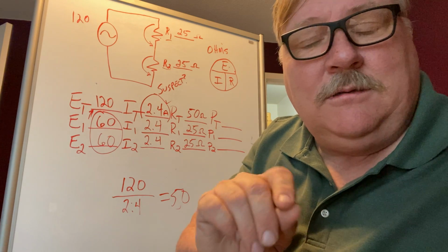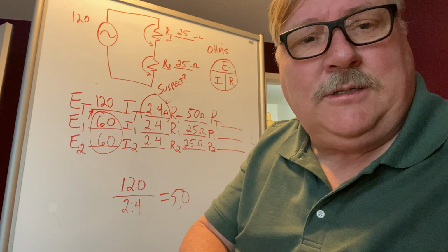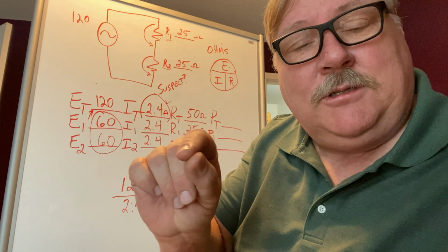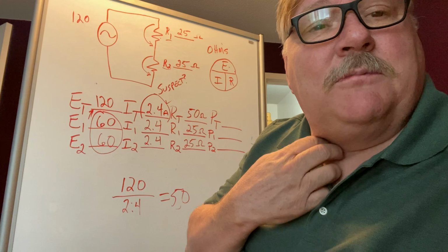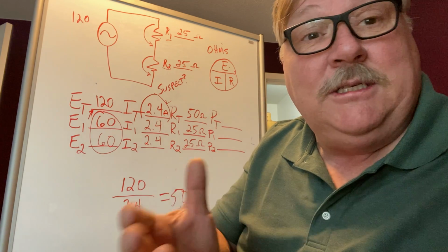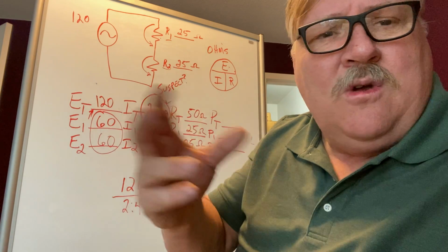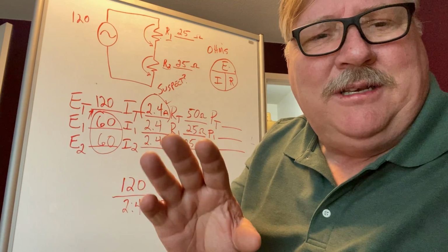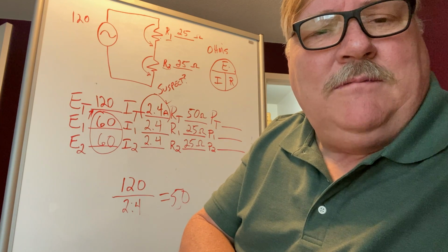Because you have to account for all of the electricity in that circuit, okay? This will come in handy in troubleshooting, because you can do voltage drops across 2 pieces of your circuit, and if your numbers don't come up with your circuit total, you have an extra resistive load somewhere in there, and that could be a bad termination. That could be something that somebody's tied into your circuit and you didn't know about it. They've added a motor contactor or a light or something like that. If it's a light in that, no big deal, but if you don't have any other loads on there, you've got a bad connection somewhere, okay?